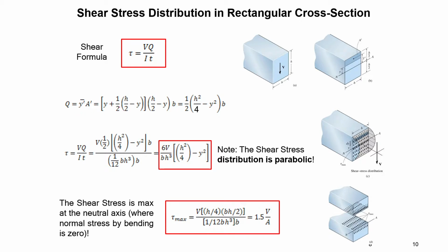So talking about any small area on top, this gray part, you need to use the centroid position of that small area to the distance to the neutral axis. So essentially y prime average should be equal to what? Equal to this y plus that small distance, okay?